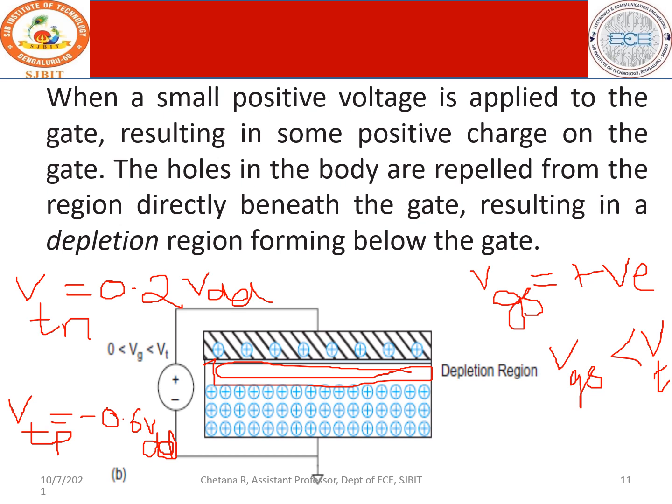These are all add-ons. Please remember this. But in the first stage, what did you see? When the voltage is initially 0, no channel is formed. Second, when you initially give a negative voltage, that is VGS less than 0, the charges are negative in the polysilicon region and as a result they get attracted, and that is called the accumulation mode.